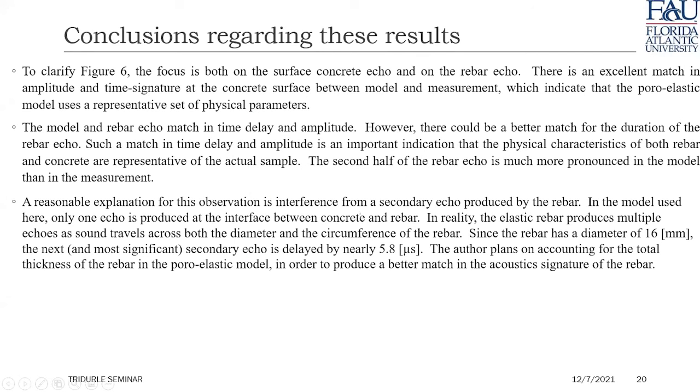This has to do with the fact that the sound travels as the impulse hits the rebar. It travels through the rebar and bounces, and it causes the rebar to vibrate and oscillate on its own. And we're improving the biomodel to perform a better match, accounting for the thickness of the rebar itself in our model. This is where we are right now.